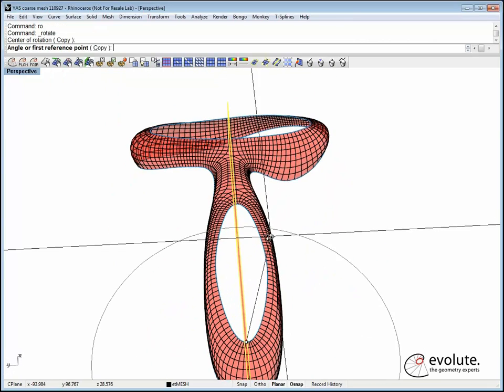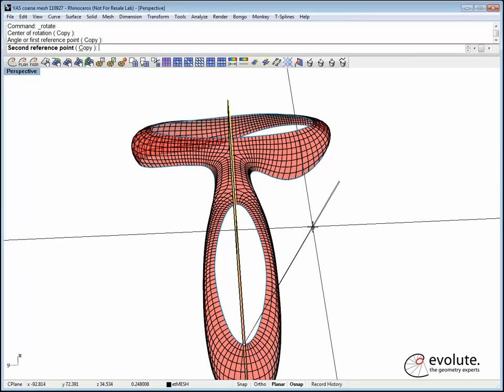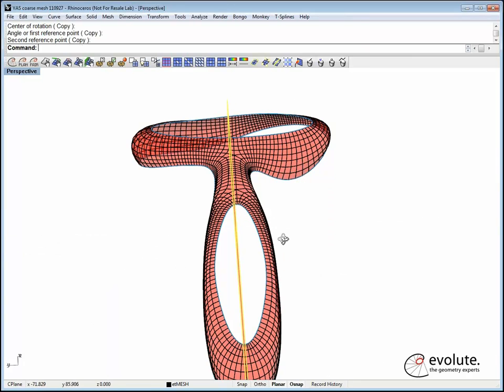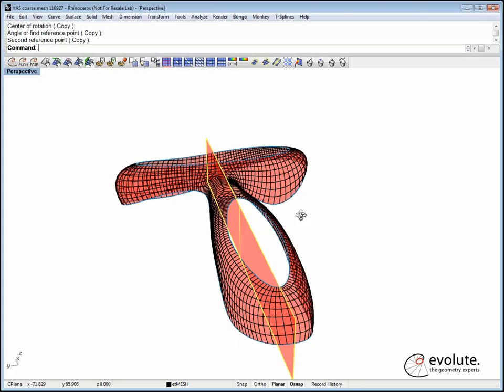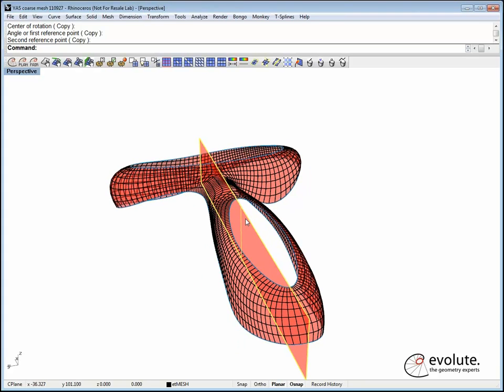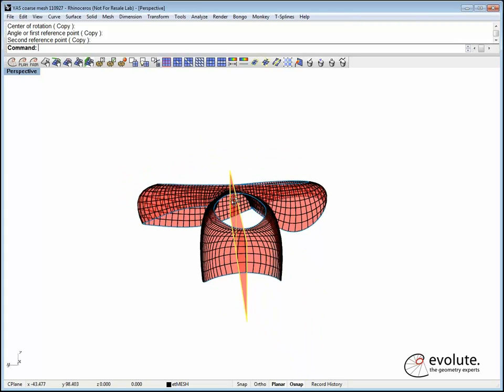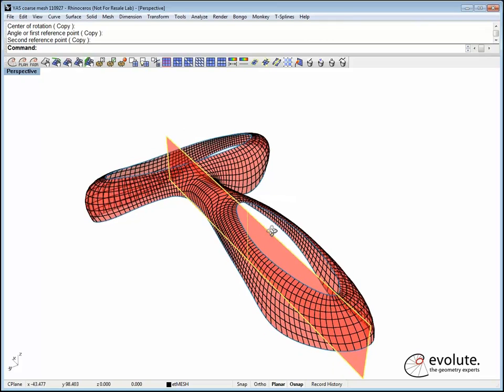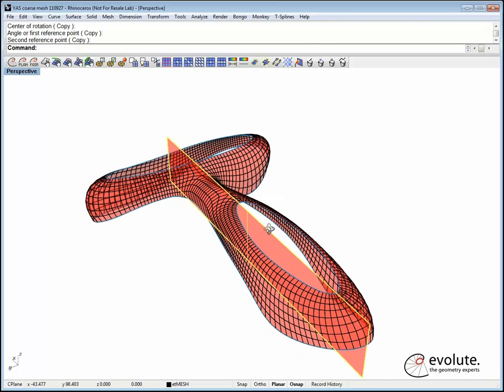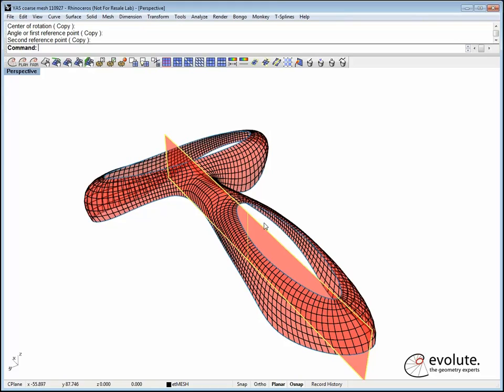Unfortunately, this doesn't mean that automatically those sets of vertices will become coplanar in this one. Select to show the plane. This is basically just a normal Rhino object that shows which was the plane where those vertices sit. So what I will do now is set those sets of vertices to become coplanar, but to stay in this actual plane I rotated about.